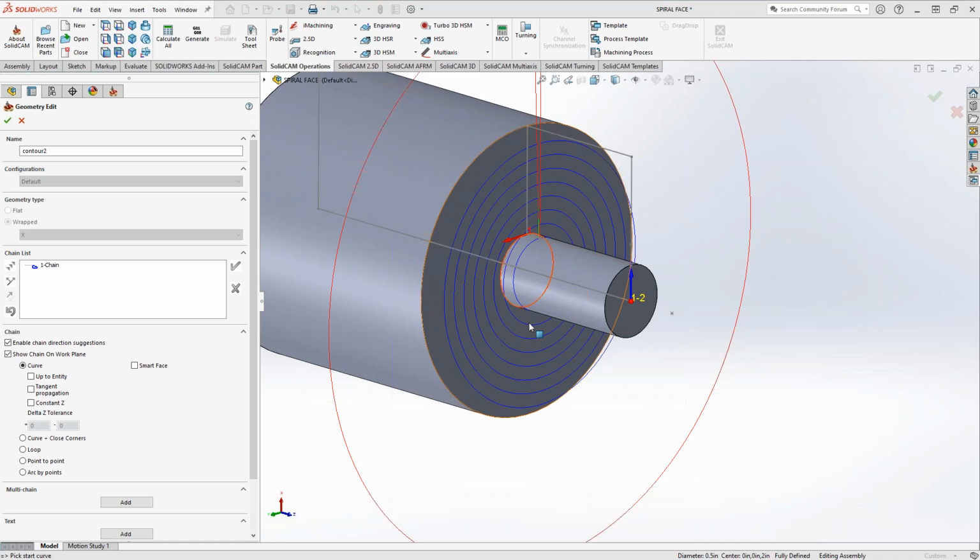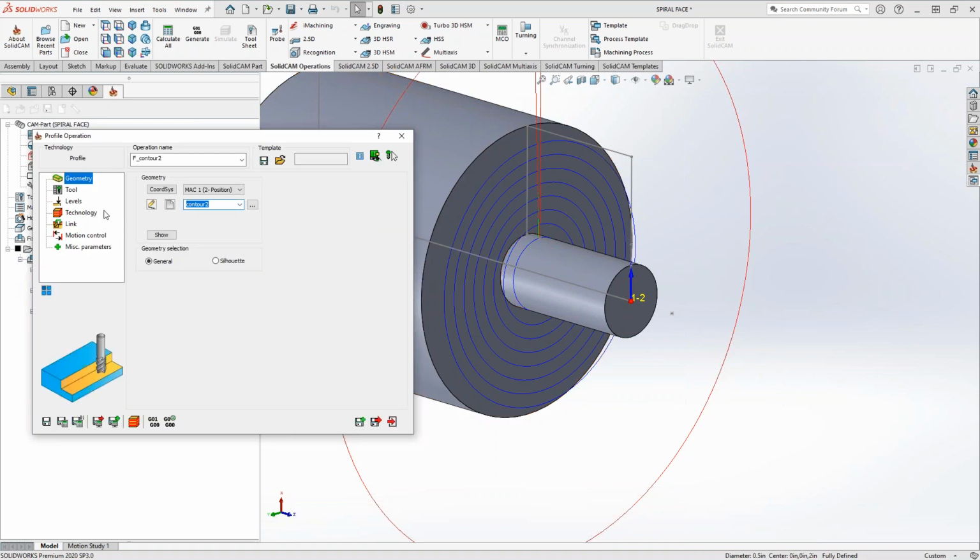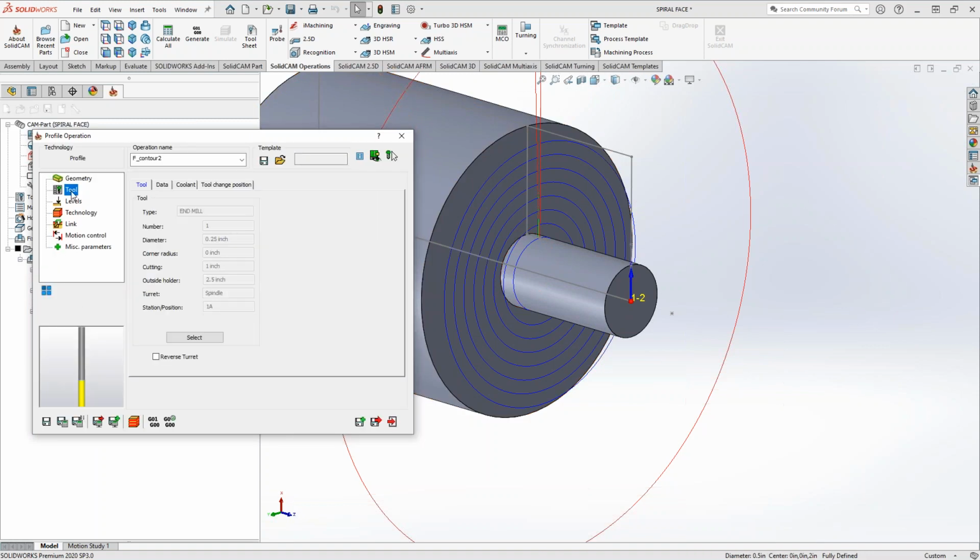You can do it with any of the 2.5D toolpaths. Pocket, profile, 3D contour, you don't want to do it like that, but there's other ways you can do 3D contour. But pretty much anything that could be wrapped with a simple radius, you want to do it this way. And then once you click that geometry, we can go to our tool like we normally would. You can use any milling tool. So if I wanted to, let's say, add a chamfer on the edge here, I could do that. I could just grab this edge, wrap it around the X-axis, and then get it to do that.